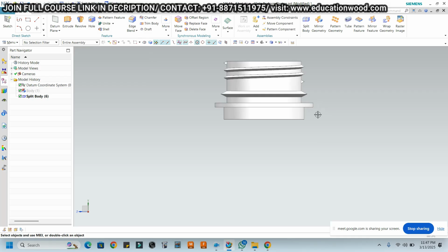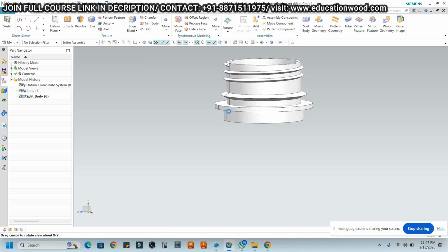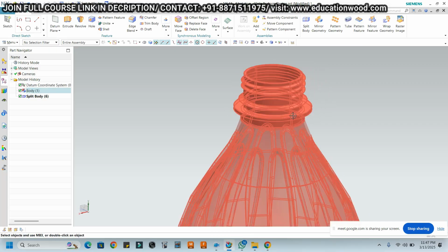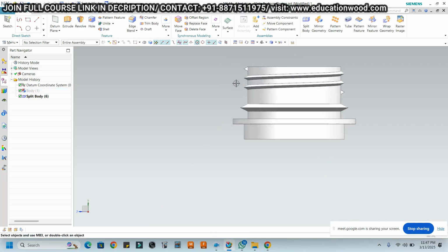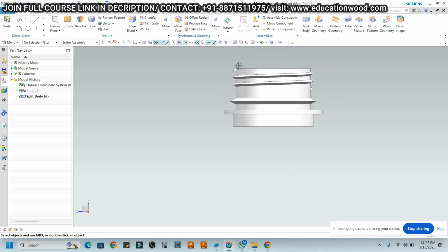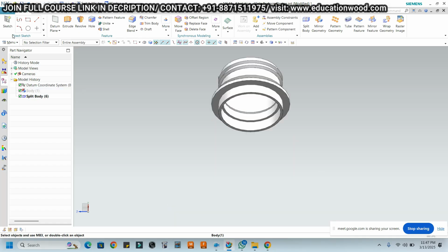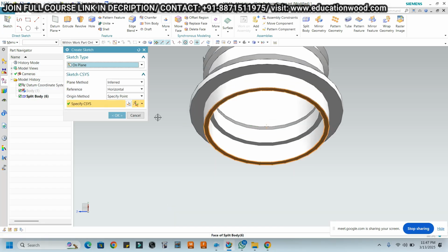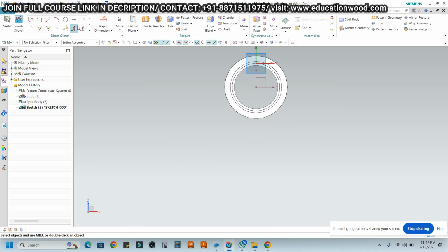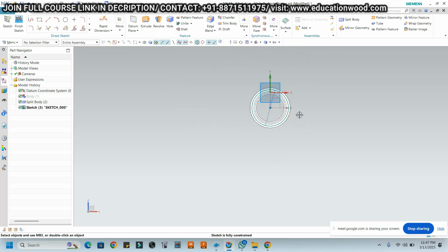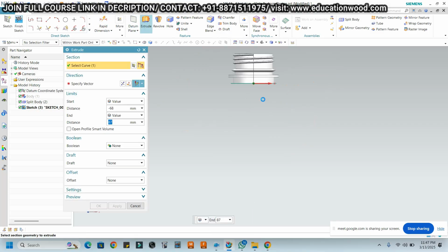You see this portion, this is the locking purpose, to lock with the mold. Basically the Parison neck will be the fixed constant on the mold. The neck is the constant, right? So here, what is the diameter which we have here? 30 mm is the diameter. The depth is 96. So 96 is the depth.